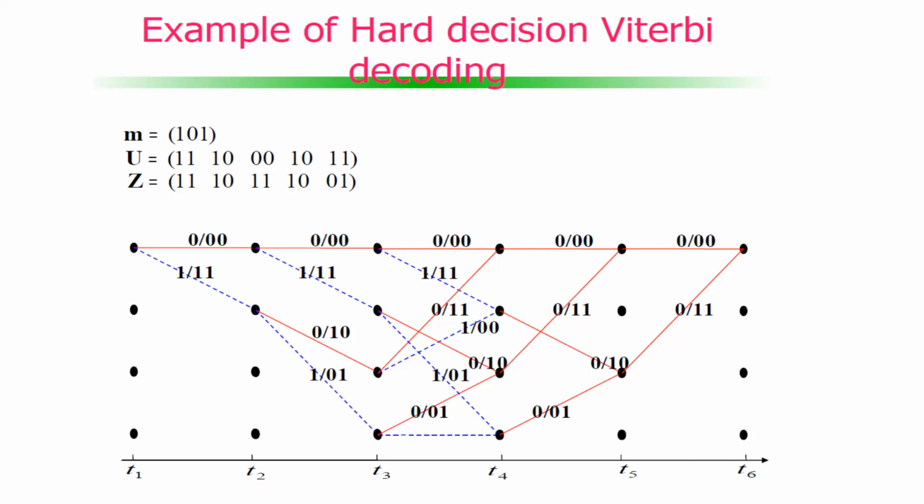So at the receiver, we have to actually decode and estimate the data. For that, we can use either the brute force approach or the Viterbi algorithm. The problem with the brute force approach is that the computational complexity is huge. Now we need to use the Viterbi algorithm.